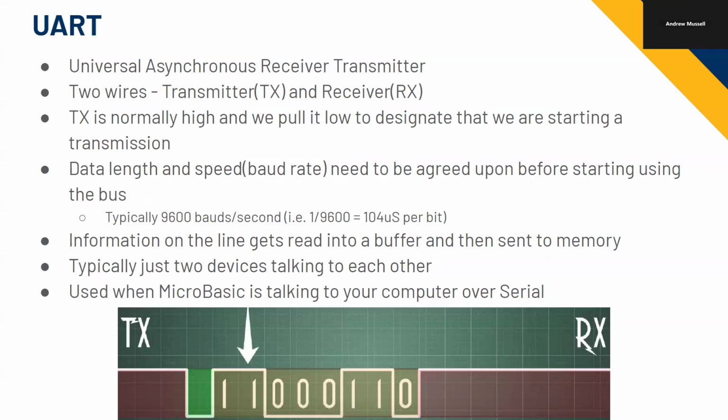And then when you scope it out with an oscilloscope, you'll be able to see a waveform like this one on the bottom, where you can see the start bit, and then you'll be able to tell high or low, and you can actually decode messages on an oscilloscope. Typical baud rates are 9600 baud, or a lot of times we'll have 115,200, which is a common baud rate.